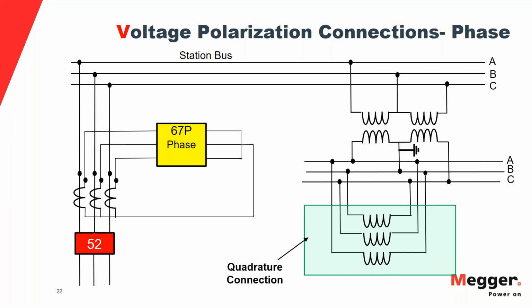Next question. When performing in-service measurements on a directional relay with quadrature connection, would it be correct that the IA load current would typically lag VBC by 30 degrees if the load is at unity, assuming ABC sequence? I would say it will lag 30 degrees by VA, not VBC. VA and VBC in an ideal world are lagged by 90 degrees. So probably VBC would have a 60 degree difference with IA.